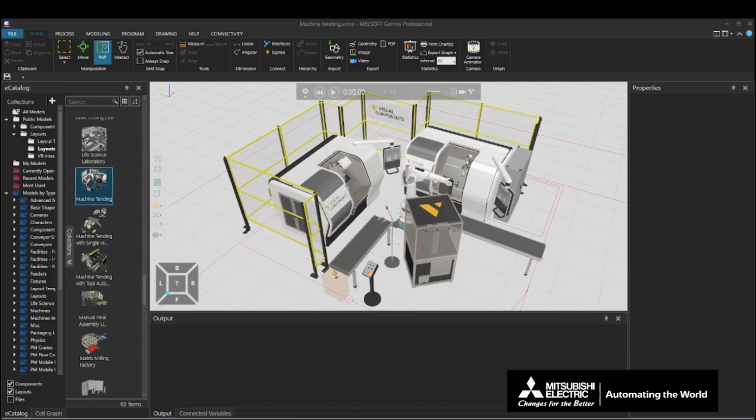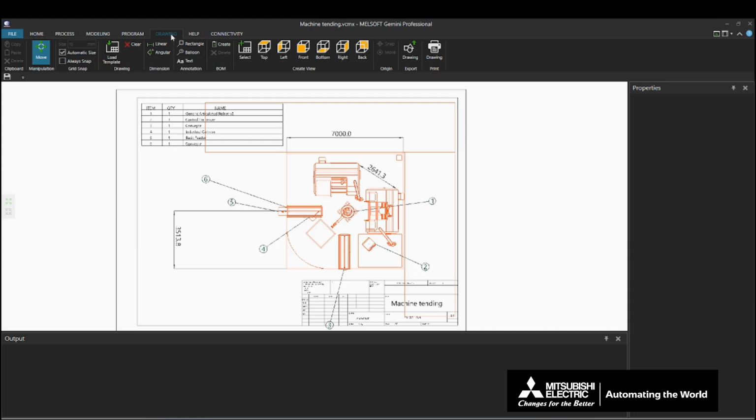This section will now explain about the Drawing tab. The Drawing tab expresses the 3D world layout with 2D drawings such as lines and points. Click the Drawing tab. This will display the current 3D world layout with 2D drawings. Clear the current screen. Go to the Drawing group and click Clear to delete any displayed drawings.